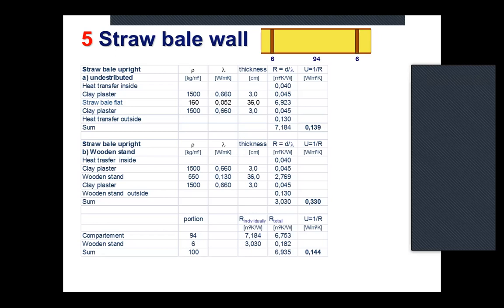Yeah, from the point of view of the total wall, it's not so much worse, you are right, but there's another thing which we don't take into consideration here, and that is, for example, the local temperature at that point. Because there could be a bigger thermal bridge at this point of the post. It's more obvious in the example where such a thin post could be metal.